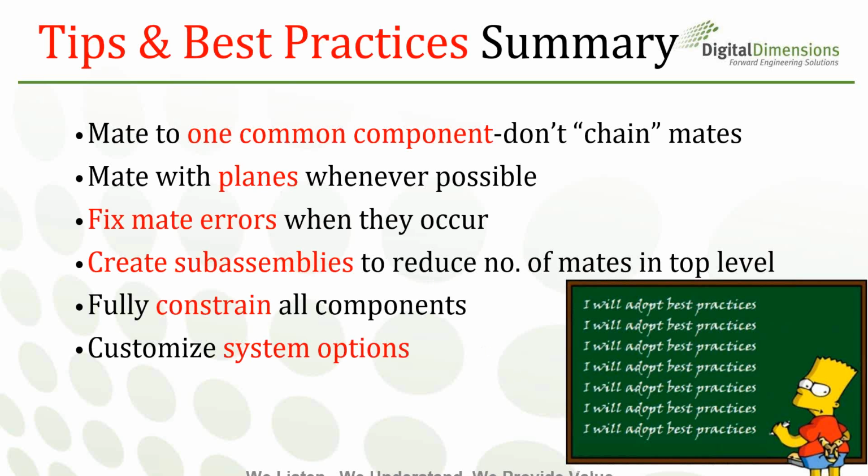And don't forget about customizing those system options first. If you know you're going to be dealing with assemblies of certain sizes, go in there, turn those checkboxes on under the system options for performance and assemblies, and get all that set up to best suit your needs.